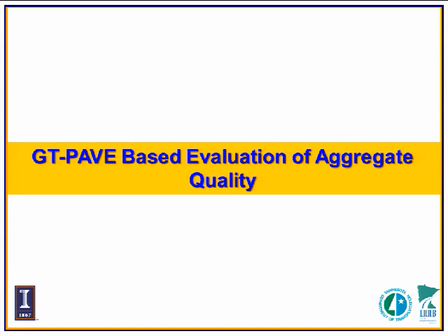This part is just, first of all, we select 3 different quality levels for aggregate base and sub-base materials, and then use GT-PAVE to get one equivalent resilient modulus for input into the MnPave program. Then we got some pavement performance from a mechanistic pavement design perspective. And in that analysis, we didn't consider some important factors. For example, we didn't consider base rutting and sub-base rutting. We only consider subgrade rutting. And the second thing, we used linear elastic analysis.